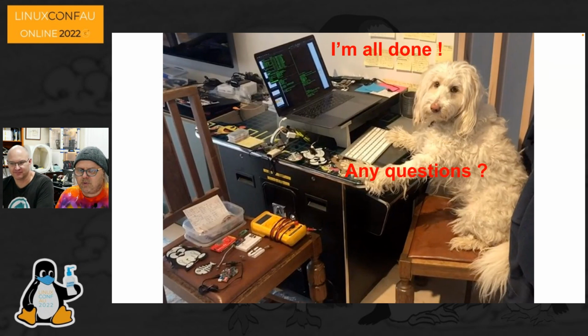Another situation people are looking at is with CMOS transistors. Whenever you change state, that consumes power. If the transistor is not switching, it doesn't use any power. So with an FPGA, you can minimize the number of transistors to just what you need. So for people who are playing with neural networks where they only need single bit, they don't need 8-bit or full 32-bit numbers, applying an FPGA to small neural networks to save power is another option.